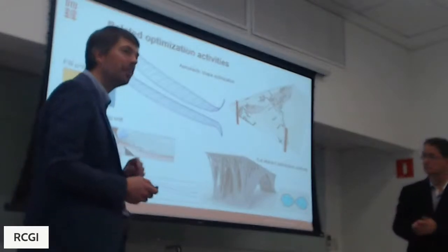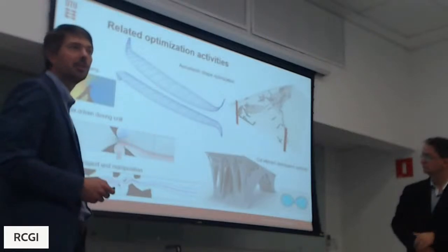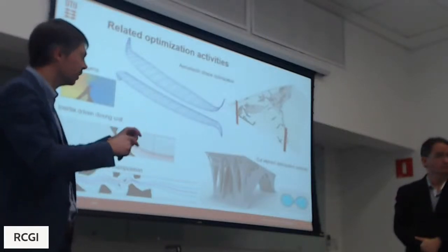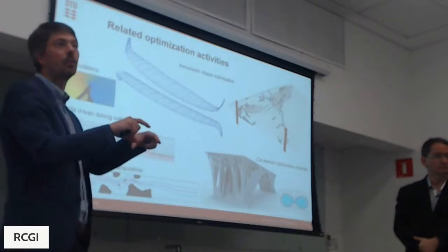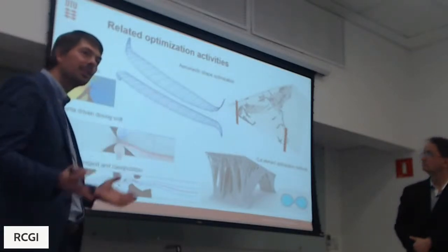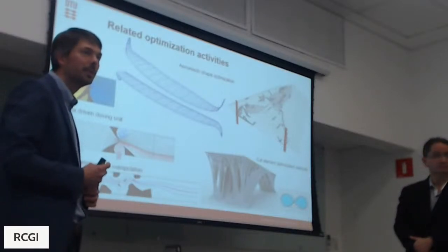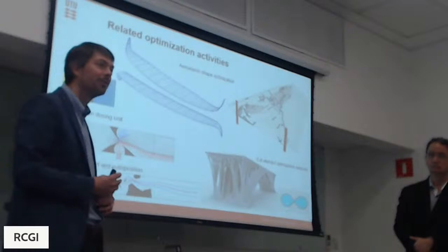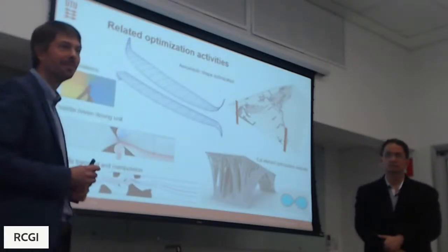For the individual element, you would do a semi-analytical perturbation strategy. For instance, in 2D there would be 4 nodes, so you just need to perturb at least 3 nodes in order to find the sensitivity. And since the interface is not covering a large portion, it's not so critical. But you could of course also just differentiate, though then you need to differentiate at each Gauss point, for instance, and that adds up.